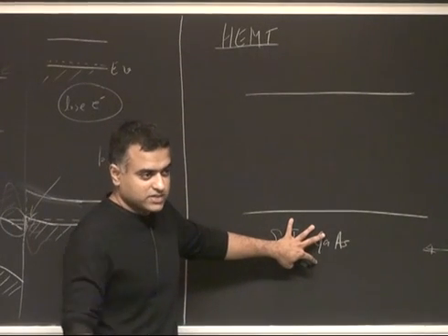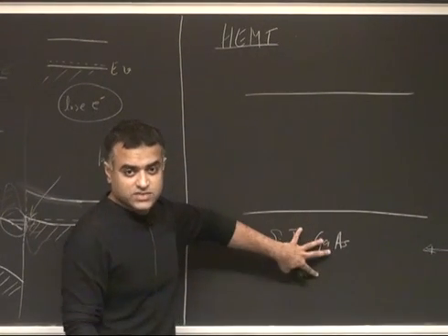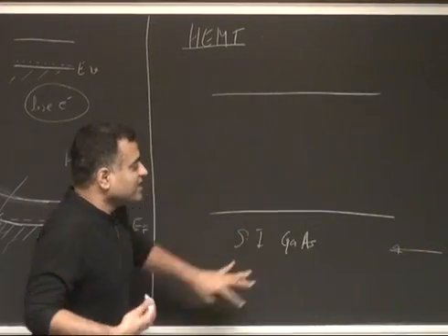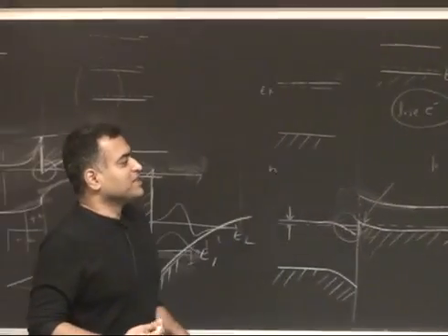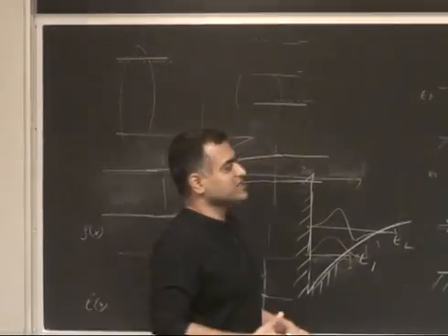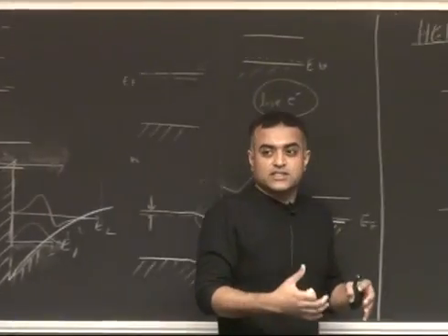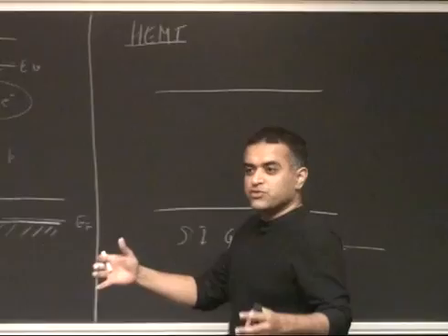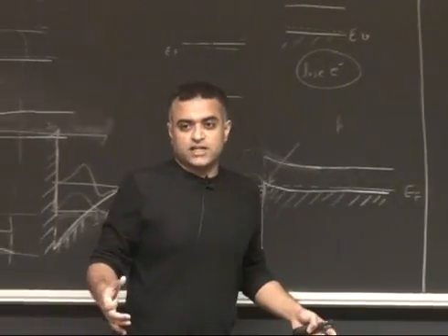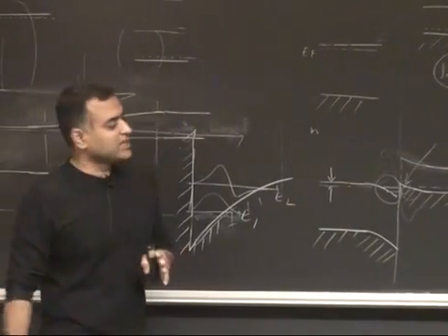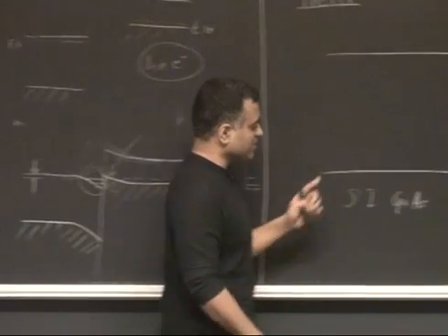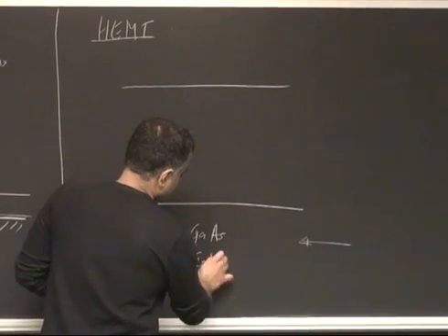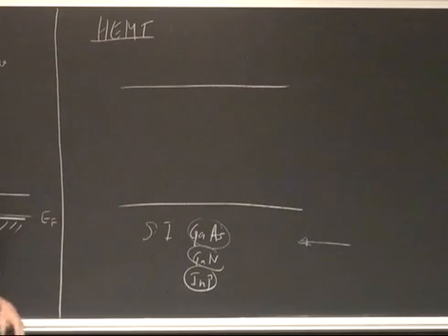So that's the isolation. When you turn off a transistor, this is what's going to keep it off. The usefulness of a transistor is really not its on state. The usefulness is that something is on and you can turn it off, right? Because a metal will always give you a very high current. There's no problem with the on state at all. Right? The off state is the key, and semi-insulating gallium arsenide, or semi-insulating gallium nitride or indium phosphide, whichever way you look at it, is a very interesting material.